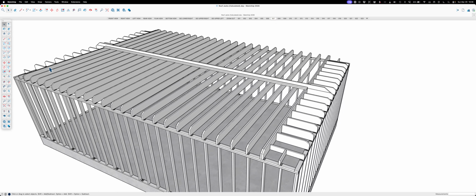So you've got your joists in, you got your blocking in, and your stiff back. So if you pay attention to what's coming next while you're framing, you'll snap a line down there, and you'll nail this flat board first. And these, you can pre-lay all that out so that you just kind of step on the board and lightly step on the loose joist, and it'll move left or right as we're oriented. And then you can shoot 2 nails down into it all the way along. So you get these all nailed together.